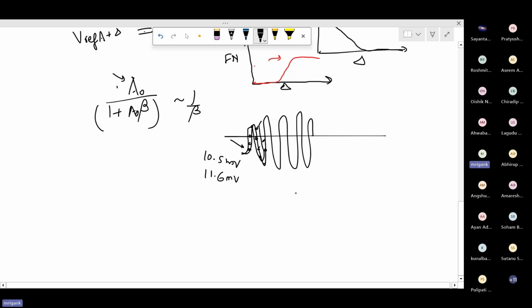Even if there is a distortion in linearity, we are okay as long as it is amplifying the signal. So some of these constraints related to the linearity and the precision will also be relaxed in this case, because we are not concerned with exact signal level. It is not that we want exactly linear gain. If the signal is looking like this, the amplified one should be exactly linear and coming exactly like this. Even if it is slightly distorted, it is okay.